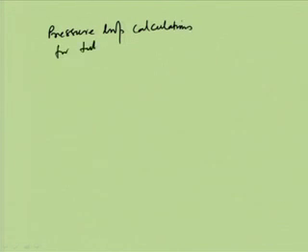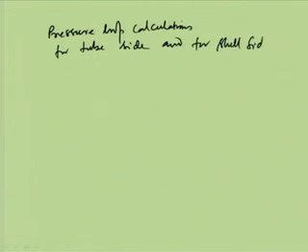If it is not, then we have to redo the calculations. That is very important to see. And then comes the pressure drop calculations for tube side and for shell side. Here also you have to check that the pressure drop is below the available limit or not.